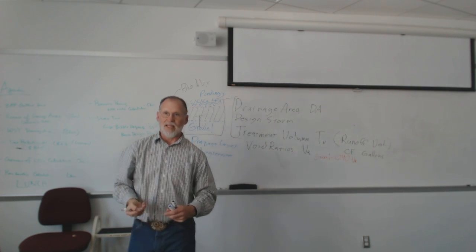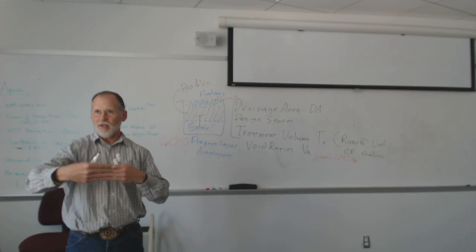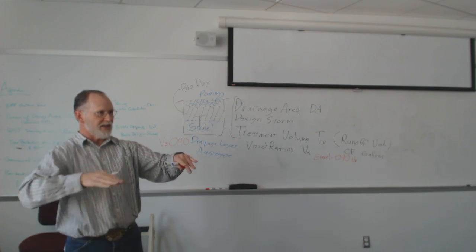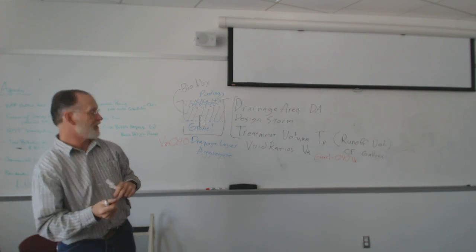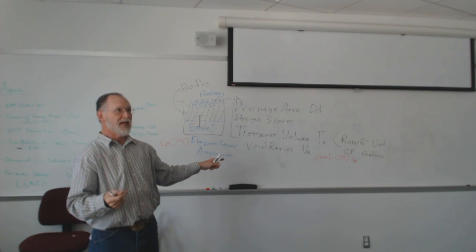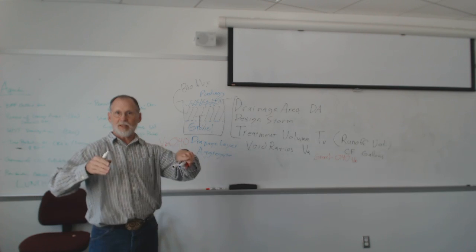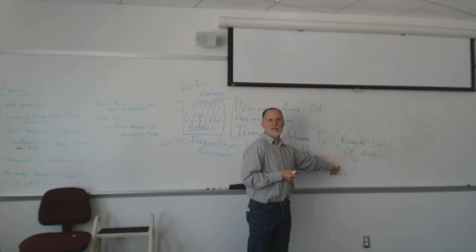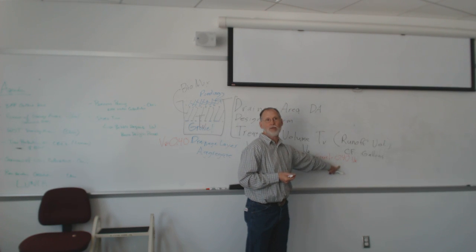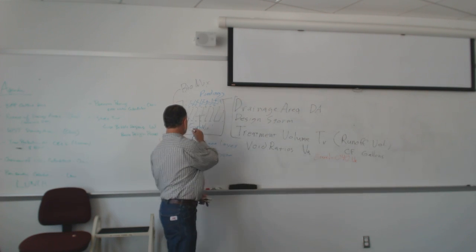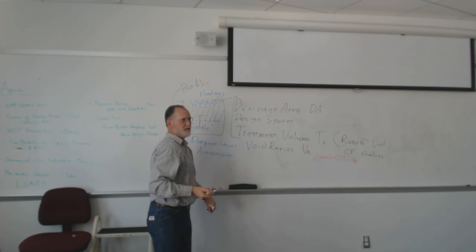So that means if you had a 1 cubic foot clear acrylic box, and you filled it up with number 57 stone, shake it, level it off, it's completely filled with number 57 stone, and it's 1 cubic foot of stone. If you fill that up with water, all the way up to the tippy top, then to drain the water out, you would get 40% of a cubic foot of water coming out of that.